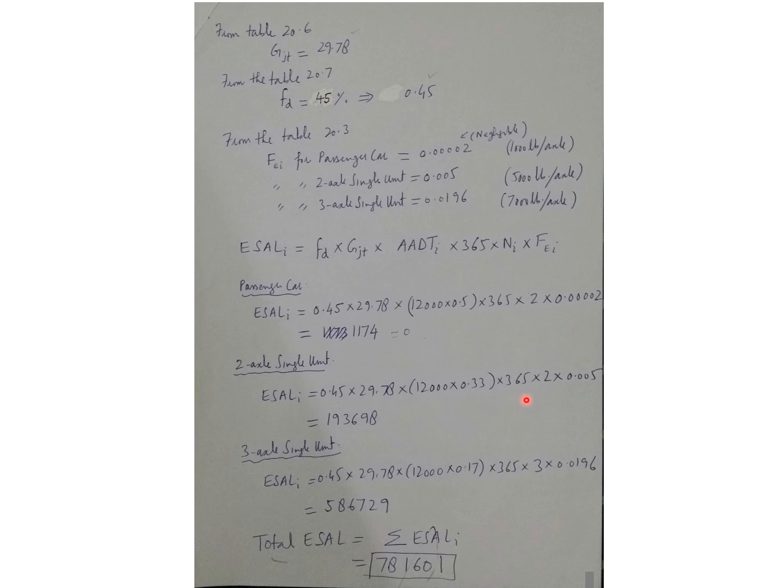Then 365, that is again 2 because the 2XL vehicles, and 0.005, that is the load equivalency factor. So the equivalent single axle load in this case is 193698.